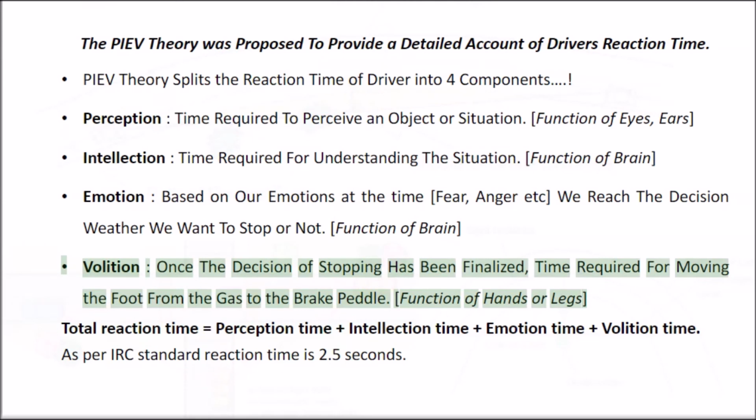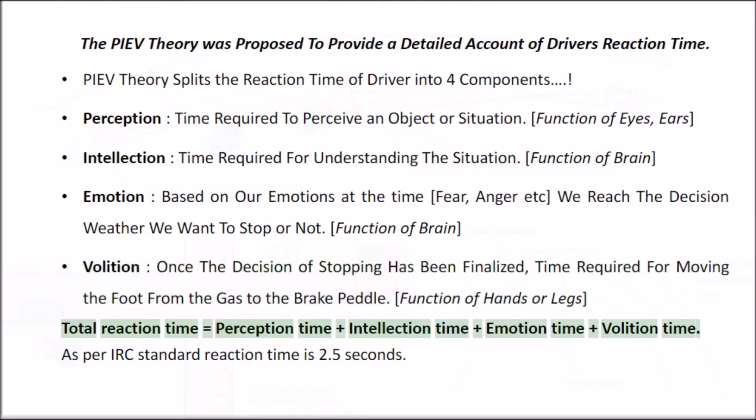Function of hands or legs. Total reaction time equals perception time plus intellection time plus emotion time plus volition time. As per IRC standard, reaction time is 2.5 seconds.